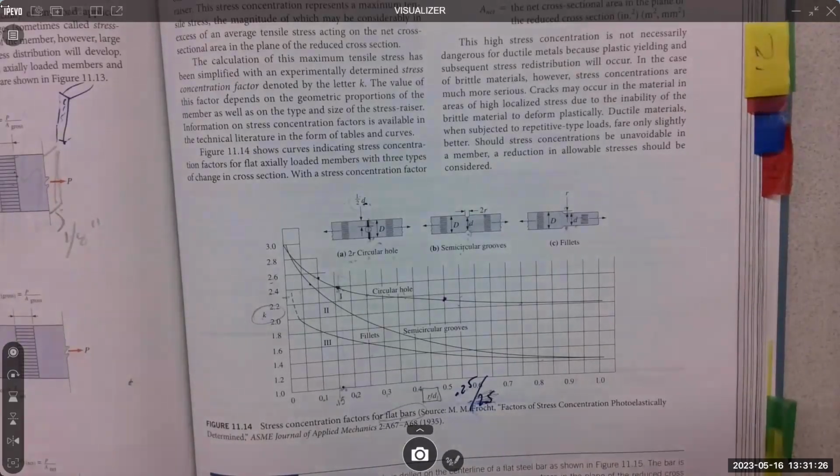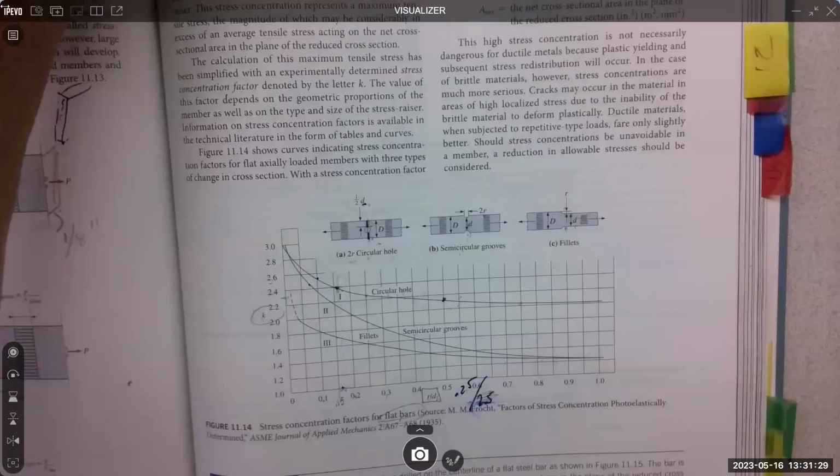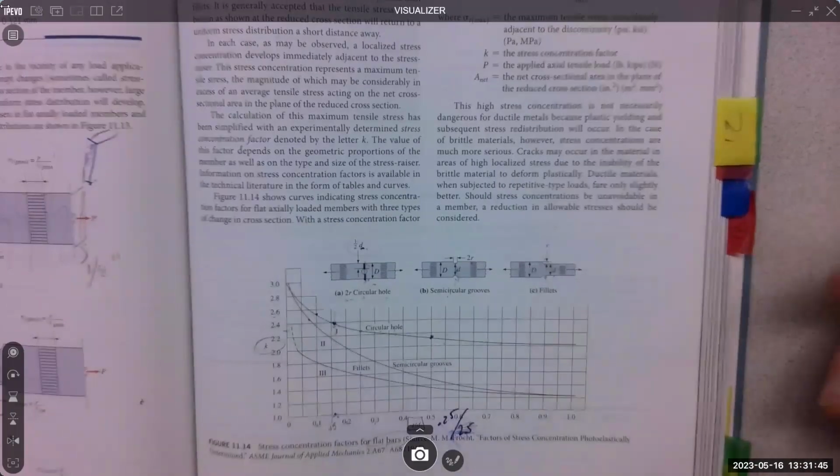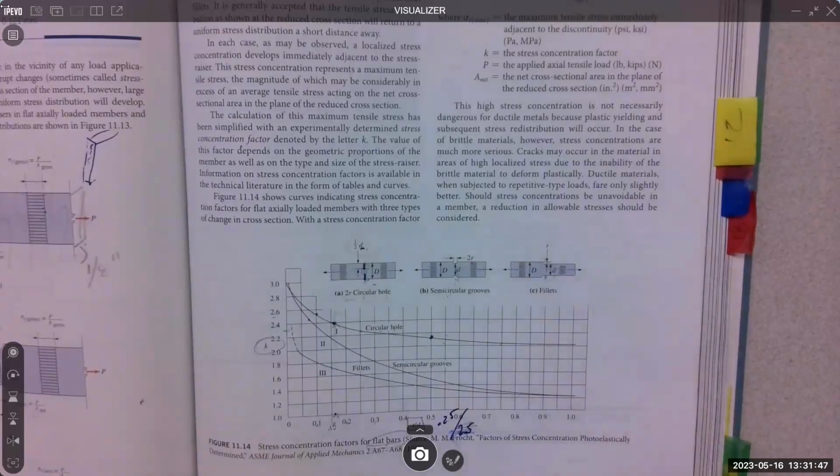That's where this is super common. But in machine parts, automotive parts, those kinds of things, it's the software-driven FEA analysis. The thing is, it seems like you don't always get great data out of a software. Sometimes the inputs are wrong. You're supposed to put in PSI here and somebody puts in KSI, or the other way around.